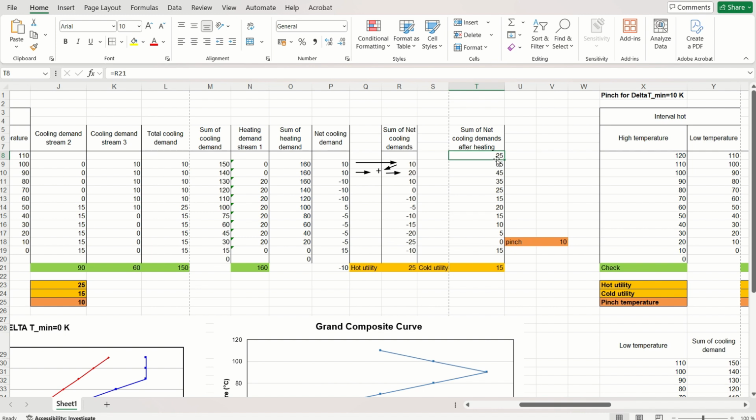Why is it calculated? Because if we add this additional heating utility within the process, then it helps us to complete the process demand. So by adding the external heating, the complete process demand, in this case minus 25, for those process streams is satisfied. So that's why we have zero at the highest deficit point, and that particular point yields us the pinch point temperature.